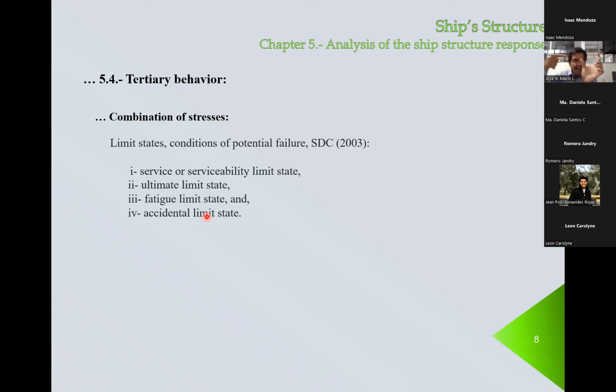But that generates an axial or a transverse load, a concentrated very high load. That's not a service limit, that's an accidental limit. And you have to think in each one of these if you want to design a safe structure.